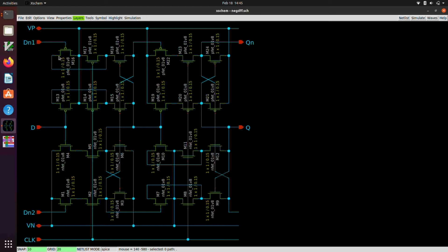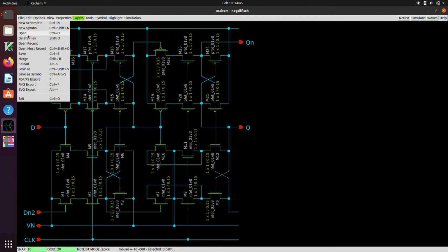And that was what you need to do if you're going to use the 3-terminal MOSFETs for your schematics to do LVS. And it was a good thing that we did LVS at this level, because we found an issue, if you recall, and we were able to make the netlist match at this level. And so to move up one level in the hierarchy, we basically changed out the ground net for the VN pin and the VDD power flag for the VP pin. Okay, and then saved it. And then I created a symbol.